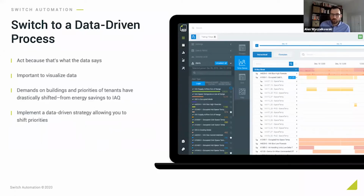So right now, maybe we're a little more focused on energy efficiency. As we open back up and people actually start to enter the building, that's when it's going to shift a little bit towards indoor air quality. So a very specific measure that you can take: let's say you do have CO2 sensors in your building, and you can monitor CO2, which is going to give you a sense of how many people are in the air, how much they're breathing in the air, releasing carbon dioxide. That's a metric that a lot of buildings will have.